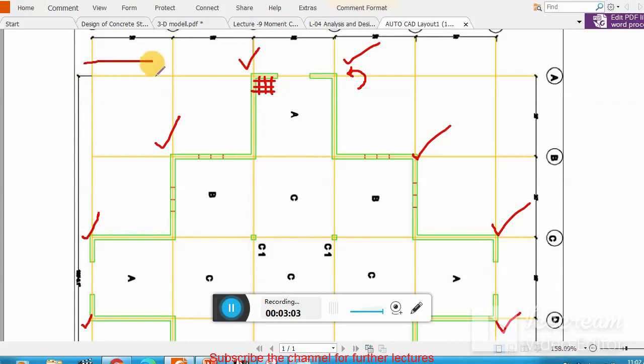Let me show you in cross section. Here is the torsional reinforcement, and that is the top bars. There are top bars, and at the lower portion as well, at the bottom of the slab. Similarly, one pattern of torsional reinforcement is that we provide this kind of reinforcement in this pattern. Clear? In diagonal form, both at the top portion and the bottom portion of the slab.